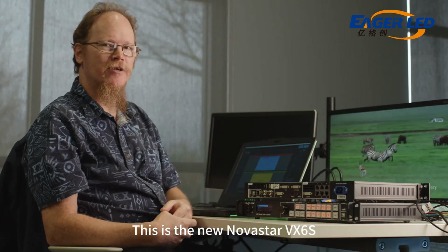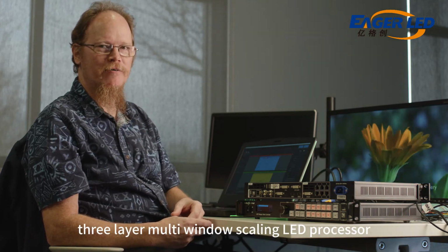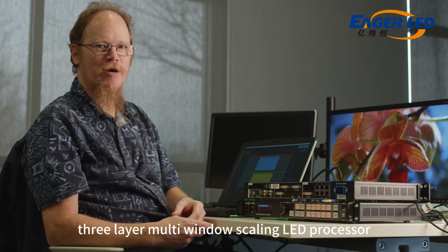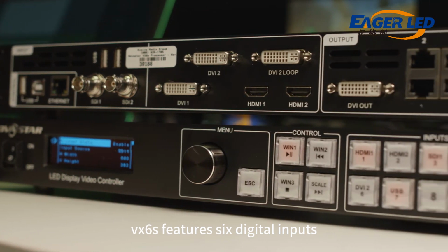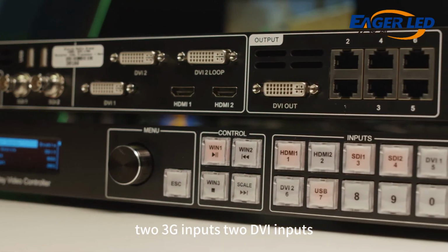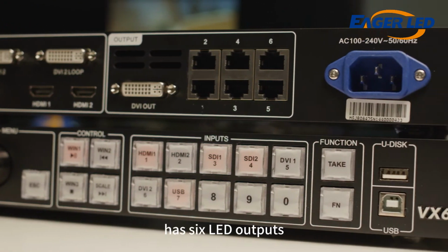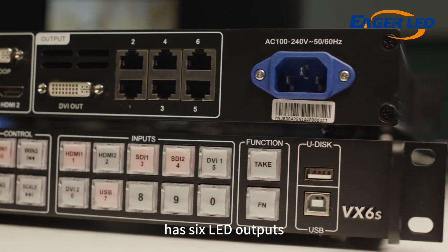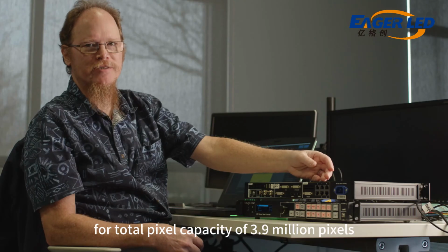This is the new Novastar VX6S, a 6-input, 3-layer, multi-window, scaling LED processor. The VX6S features 6 digital inputs: 2 3G inputs, 2 DVI inputs, 2 HDMI inputs, and has 6 LED outputs for a total pixel capacity of 3.9 million pixels.